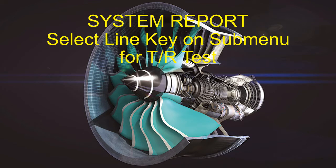Okay, and then there's a choice or sub menu after that for your thrust reverse test. Okay, so then you'll select your thrust reverse, which by the way is T/R, so you'll see that on the display, on the indication. And then you're going to start the test, let it run. Just confirm the start of the test. So you'll do that.